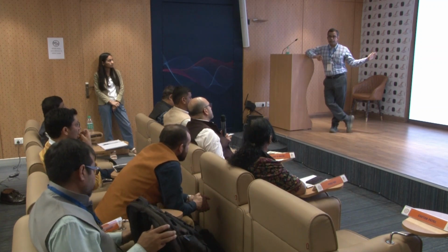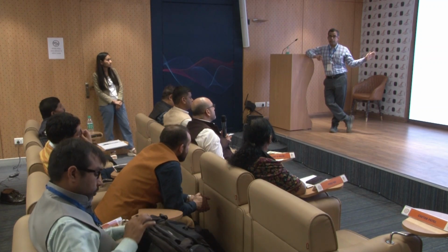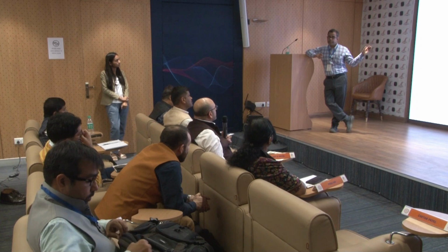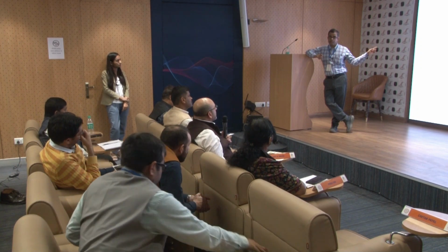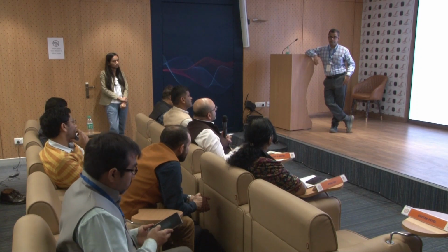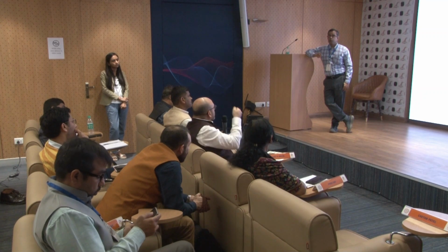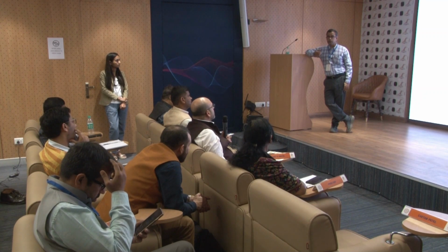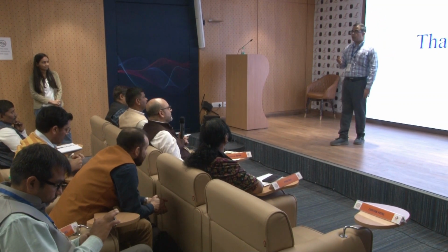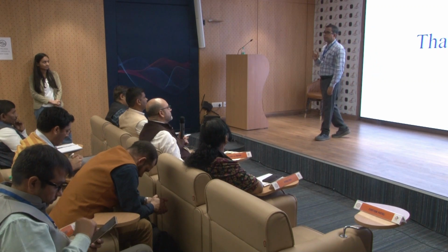Right now, in the presentation, it is just the air pressure. We are dealing with a certain diameter of the actuators, and whatever experiments have been done and shown here, the air pressure is 3 bar. But how many newtons do you use? We know the area, but I don't know the figure. Anyway, I can disclose that this experiment has a valve actuator diameter of 50 mm, sorry, 35 mm. Right now we are doing the optimizations in a different way.